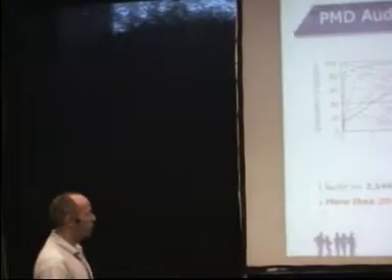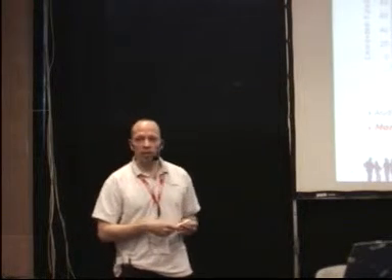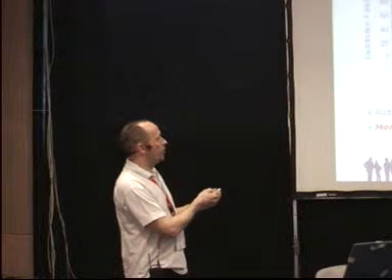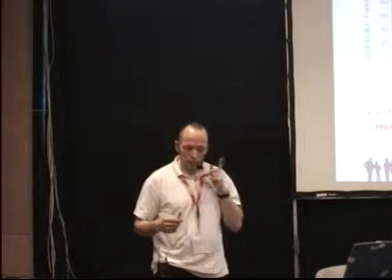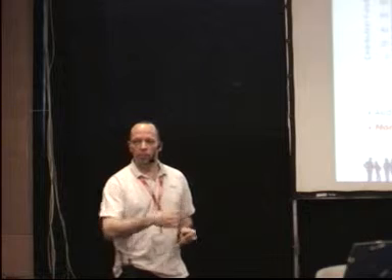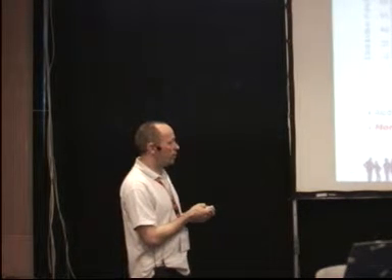This is relevant. And what they found out is that more than 20% of all installed fibers had PMD massively above all ITU standards. There is a serious amount of fibers, these here, that have more than, say, 2 or even 3 picoseconds per square root of link length as the PMD coefficient. Whatever this strange dimension means, it's simply a characteristic for measuring PMD. And the relevant standards say it has to be below 0.5 or even below 0.2 picoseconds per square root of kilometer. So keep this in mind. More than 20% of all new fibers have massive PMD, and this is not depending on the type of installation.